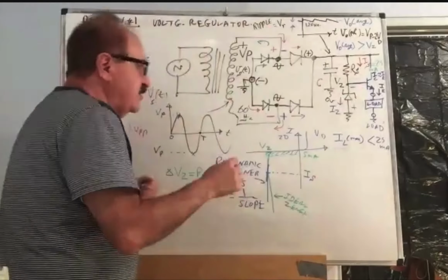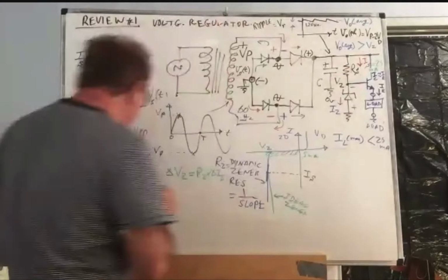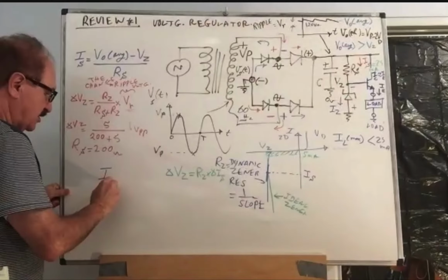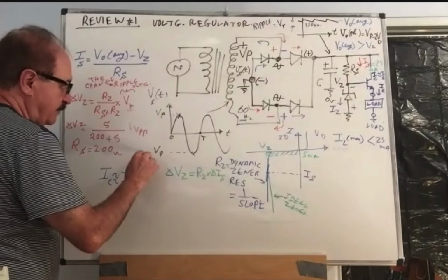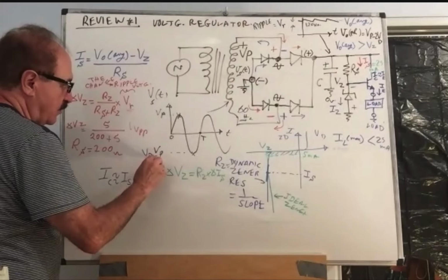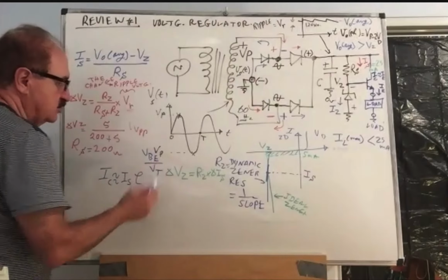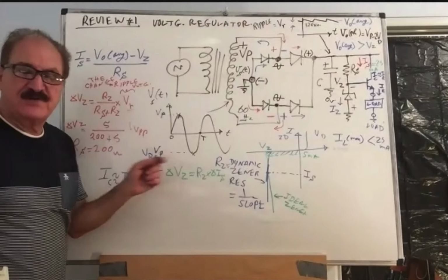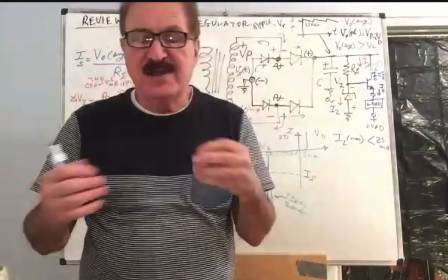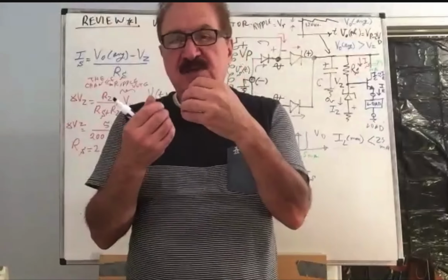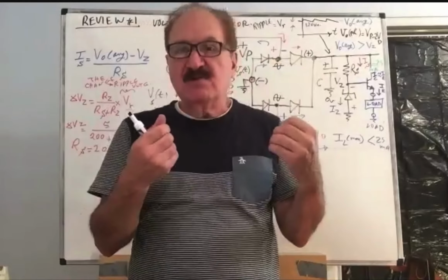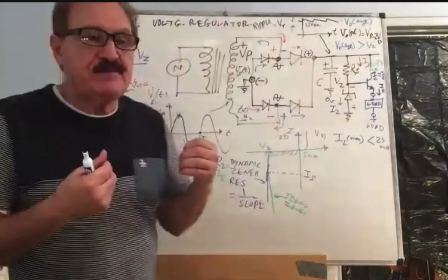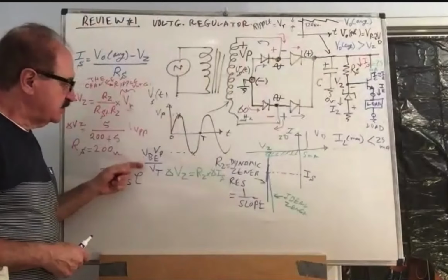Where am I computing those 25 millivolts? Remember, the current in a transistor was IC approximately IS times e to the power VBE over VT. So VBEs are 700 millivolts on average, right? But think about the difference between 700 millivolts and 750 millivolts.